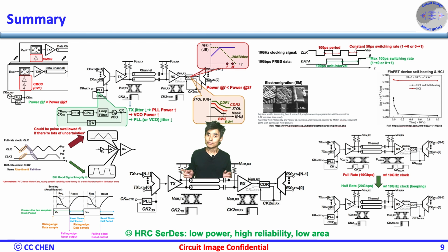In addition, for a very high density system or server, the power thermal runaway or reliability is a big concern, which can be mitigated by the hybrid clocking SerDes. For high signal integrity requirements like memory interface, automotive, industrial usage, etc., the robustness of the clock is the highest priority, and half-rate SerDes is a better choice.